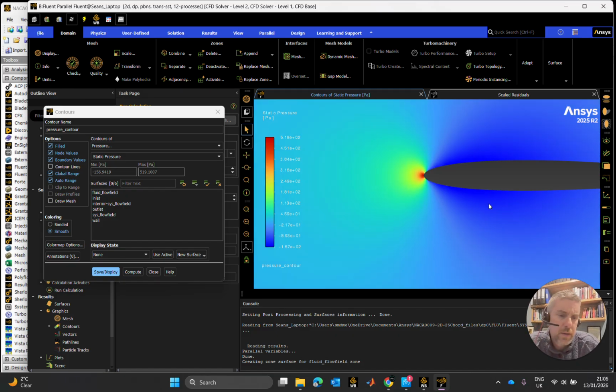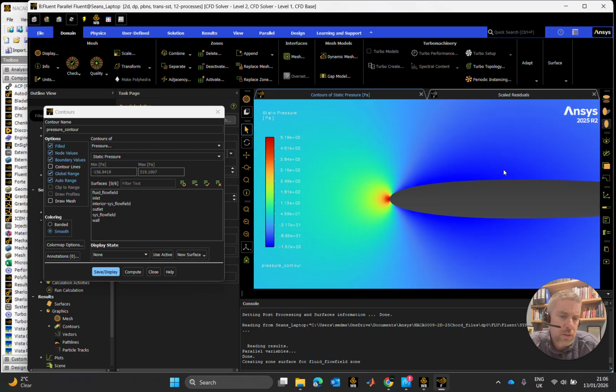according to that. Whereas when we start getting into the airfoil, we see this region where pressure is building until it hits a maximum point, a very deep red, very deep scarlet, right at the leading edge of the airfoil. And that's indicative of what we would expect. You can imagine air particles ploughing into the front of this airfoil as they approach it and eventually hit it at 29 meters per second.